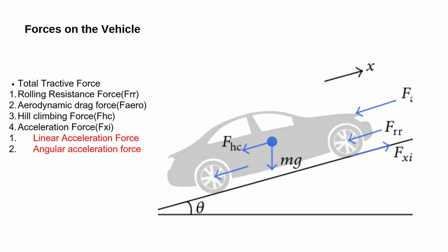Next one is the hill climbing force. This is the force required to overcome the effects of gravity when a vehicle is climbing a hill. Hill climbing force increases with the steepness of the grade and also the weight of the vehicle.